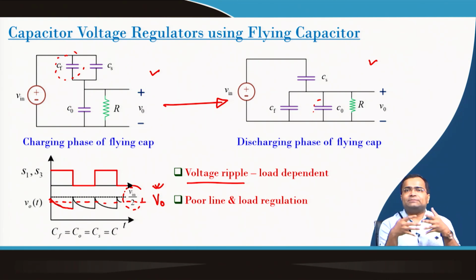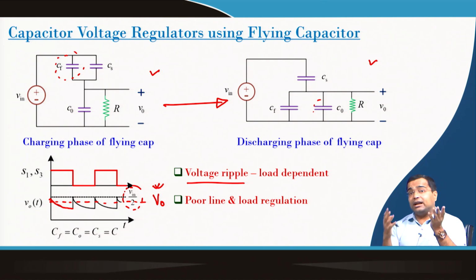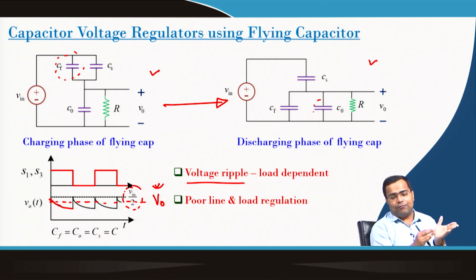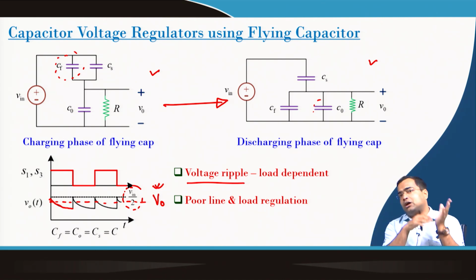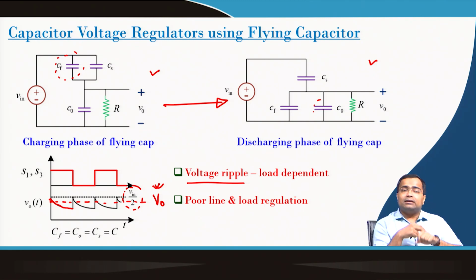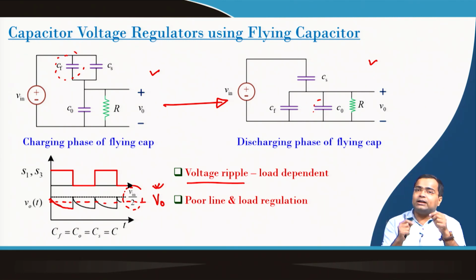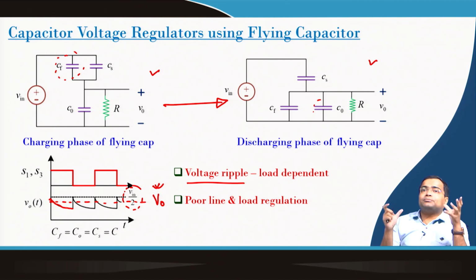So, this voltage mismatch will cause a huge inrush current. That means a huge inrush current will go from the flying capacitor to the output capacitor, and it is important to limit the current. So, we also want to make sure that a very large voltage variation is not desirable, and the amount of current also depends on the size of the output capacitor.